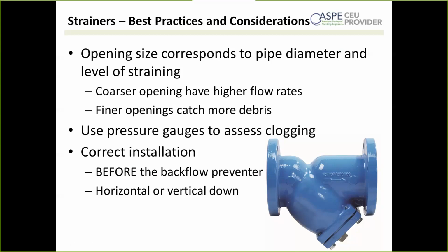Also, I do want to point out that you should check with your water authority. They're not always allowed, as the water authority sometimes wants the backflow preventer to be the first thing after the meter, and they typically aren't allowed on fire systems.